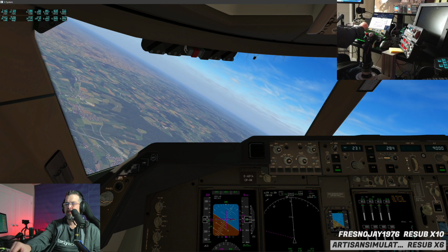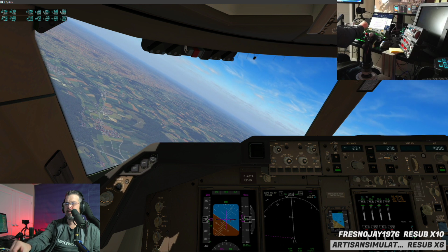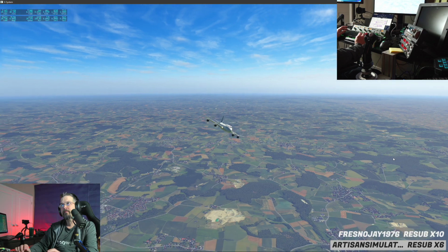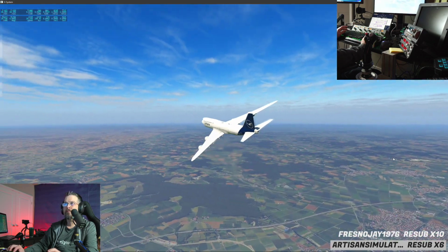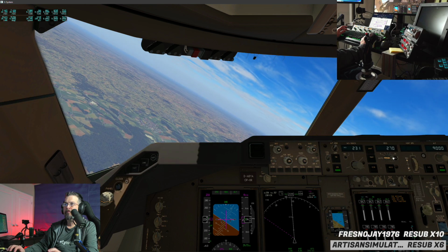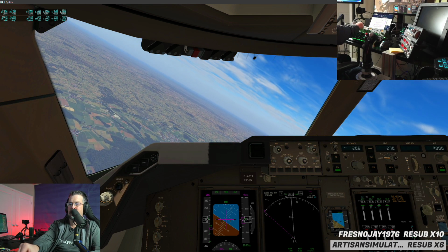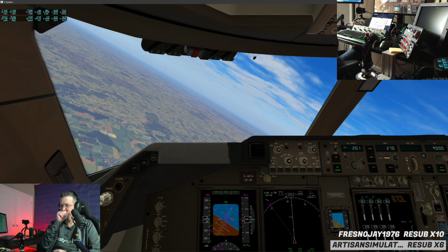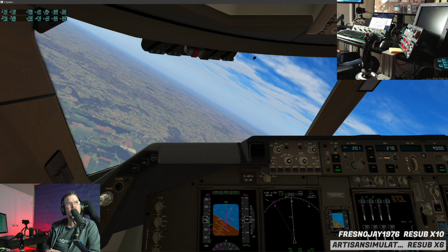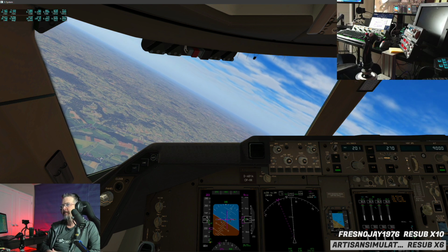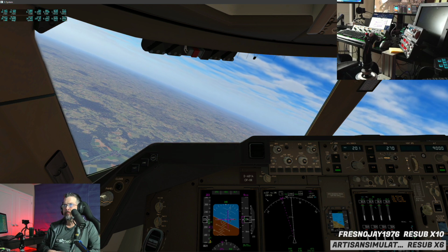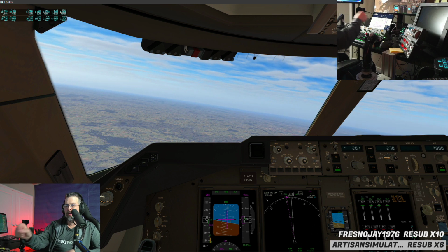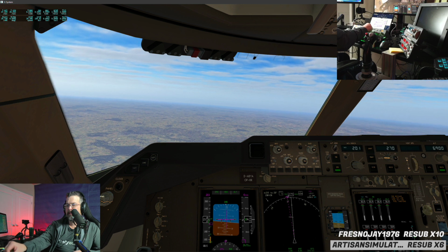Thank you, guys. All right, I'm going to fly heading 270. And I'm going to change my speed to 200. What I'm going to do is I'll do one approach with this weather condition, and then I'll probably try to do a low vis approach just for testing purposes. And I'm going to change my altitude down to 5,000.